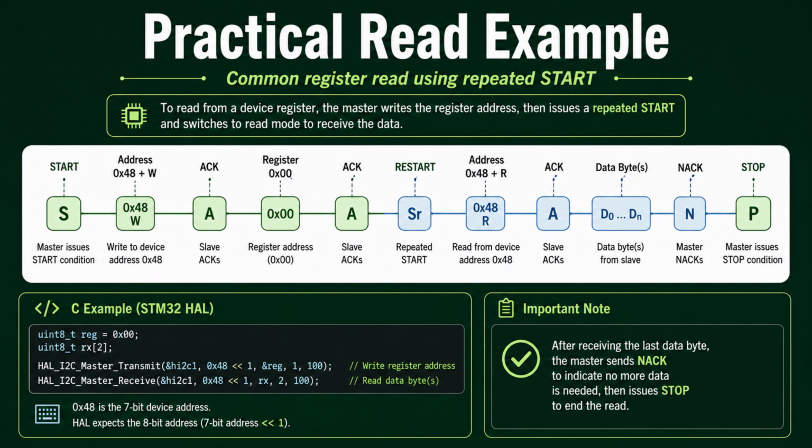For STM32 applications, functions such as HAL_I2C_Mem_Read, or the sequential transmit and receive APIs are normally more appropriate when a true repeated start is required. Two independent blocking transmit and receive calls may insert a stop between operations, depending on the driver implementation.